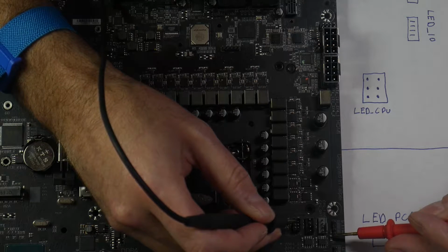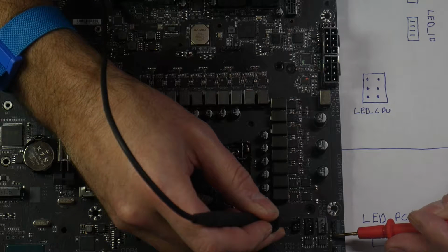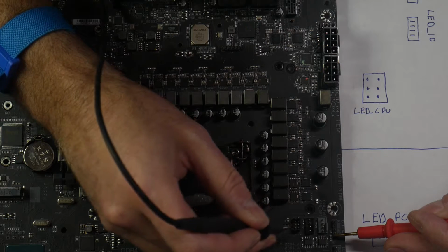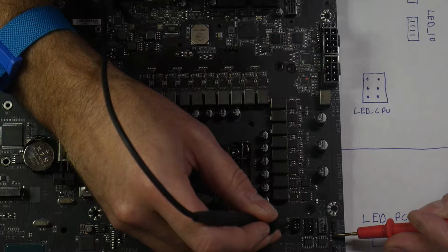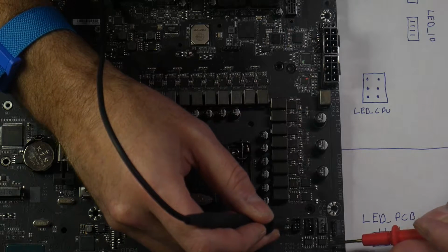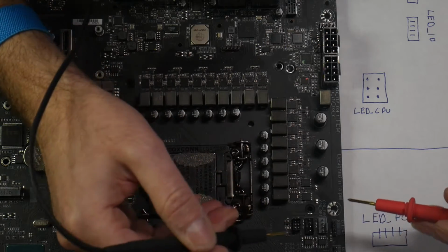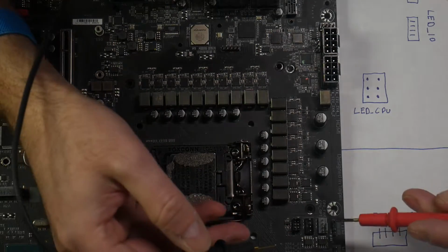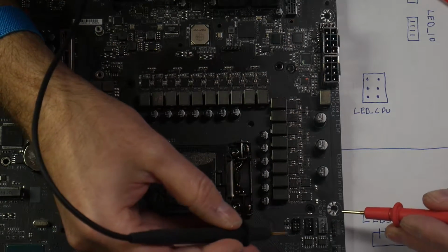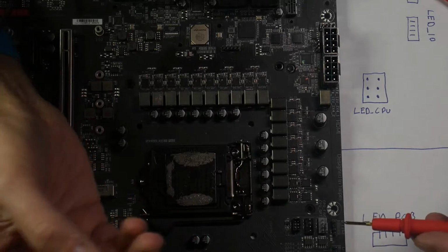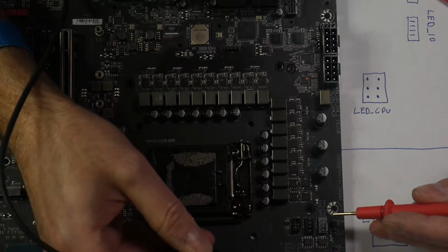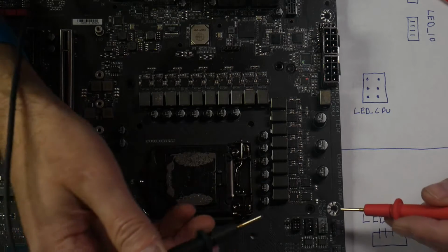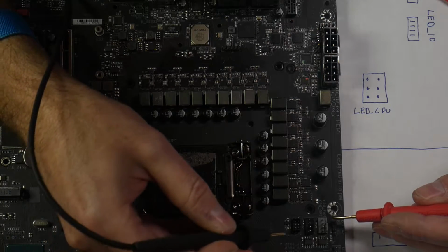If we check continuity between these two, between voltage, okay, I have continuity between that. And reverse, hey, I get continuity between both of them. So what's happening is you have what are called decoupling capacitors, and they connect to the 5 volt or 12 volt voltage and also ground. There are a few different reasons that they use them, and generally you have one next to every integrated circuit.